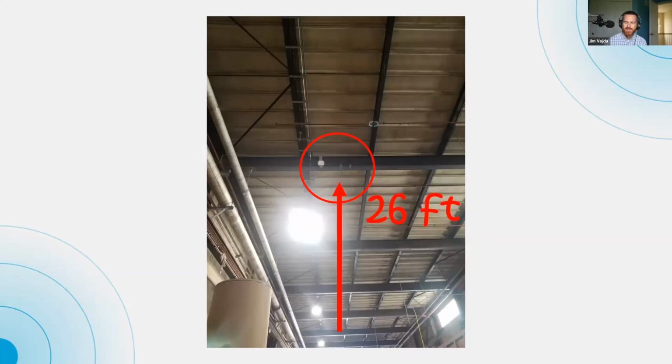Of course not. So, to get 9 dB of gain in the horizontal plane, we do that by sacrificing beam width in the vertical plane. Yep. Coverage. So your nice fat donut starts going down to this skinny little pancake. It's a disc. That frisbee of coverage, and it is also an indoor AP. So how awesome is that? I think that's the last one I got.